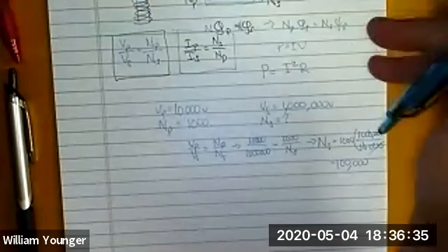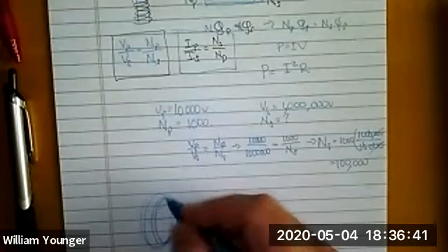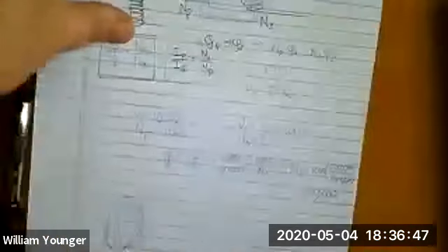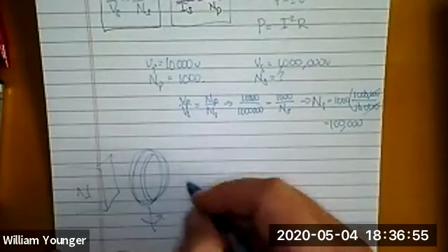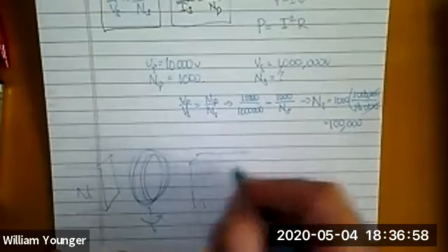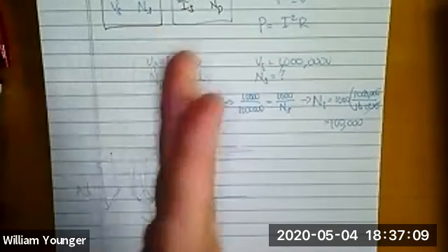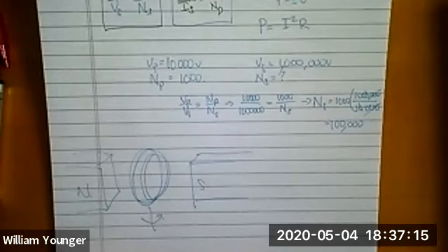Well, it turns out, thanks to our understanding now of Faraday's law, that whenever you have a coil of wire like that, and it's free to spin about some axis in a magnetic field, say between the ends of a magnet, this would be the north end and this would be the south end, then the flux is going to become a maximum when the plane of the coil is parallel to the front faces of the magnet. The flux is a maximum.